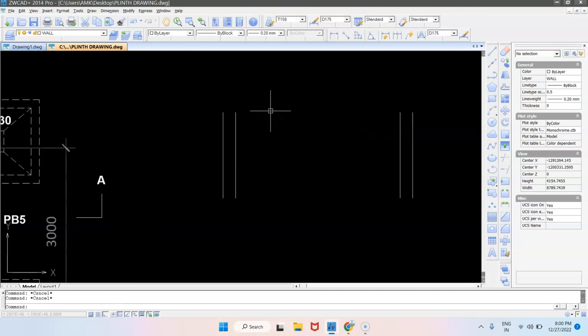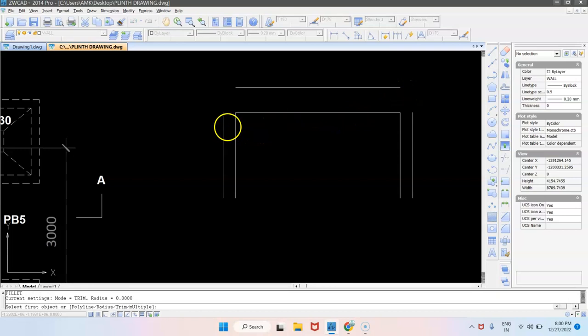Now on top of that, let us draw the beam. Let us assume the size of the beam to be 450 mm in depth, because nothing has been given to you, we will have to assume this size. So I will draw a beam of 450 depth here. So now what we have is a beam which is spanning between these two columns.